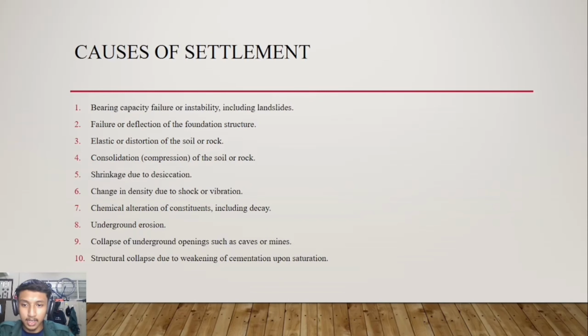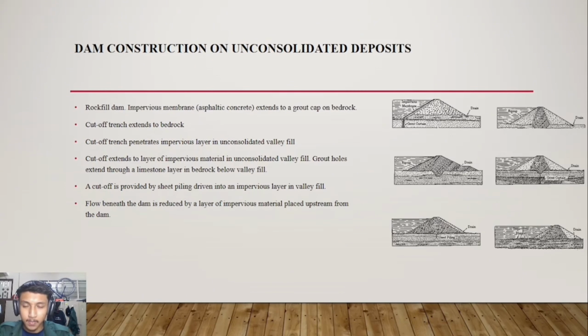Sixth, change in density due to shock or vibration. Seventh, chemical alteration of constituents, including decay. Eighth, underground erosion. Ninth, collapse of underground openings such as caves or mines. And last, structural collapse due to weakening of cementation upon saturation. So, dam construction on unconsolidated deposit.